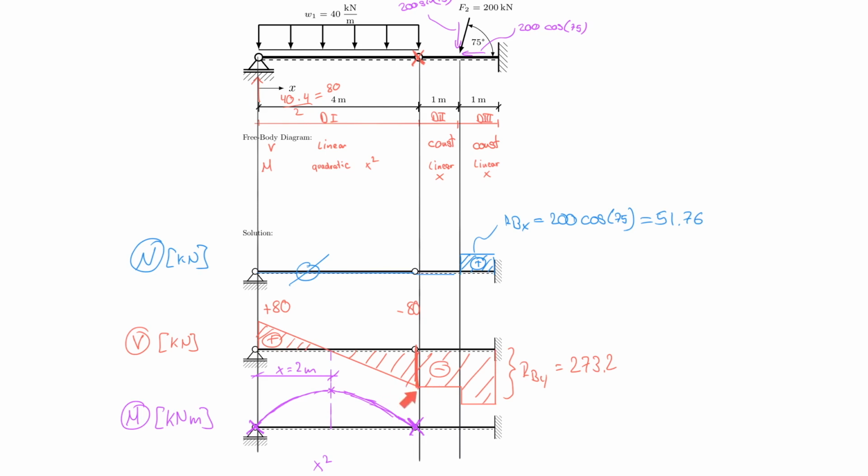What that means is that here in the moment diagram on the left side, the tangent is identical to the tangent on the right side here. And so I can therefore, not that my hand drawing can really show this, continue that tangent, which goes down. And so ideally that matches my parabola there.